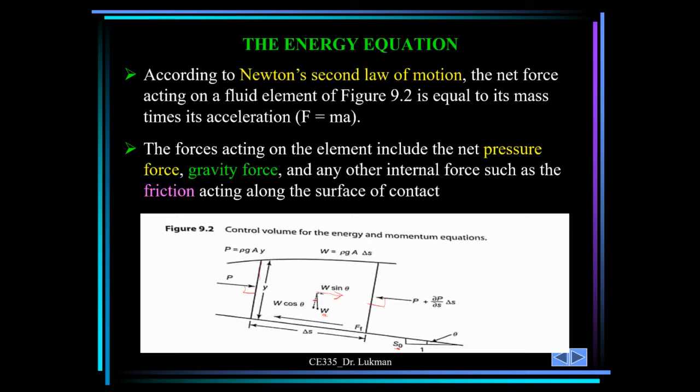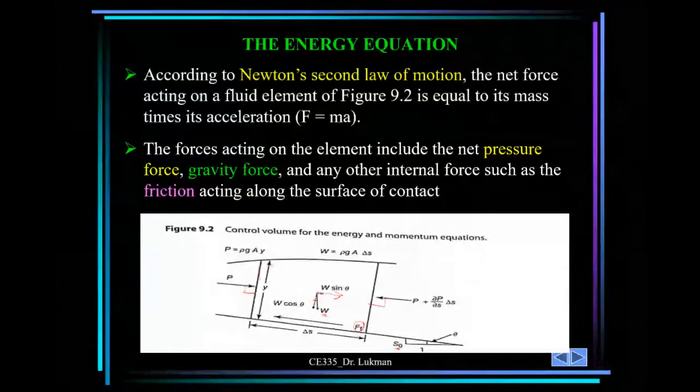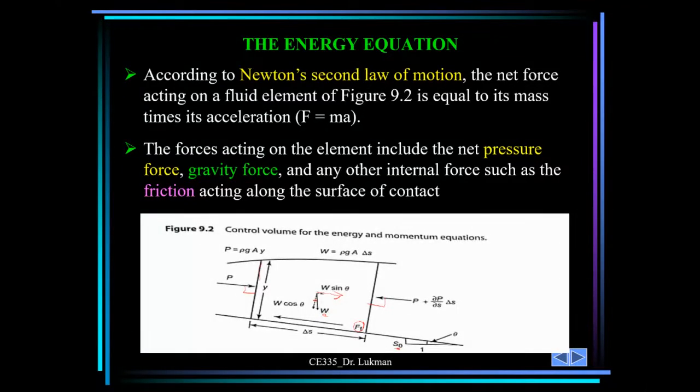And then you have any other internal force, such as the friction force, subscript D, acting along the surface of contact. In this case, the frictional force will usually be in the form of shear force, because here we have a fluid element, hence viscosity is the major cause of the shear.